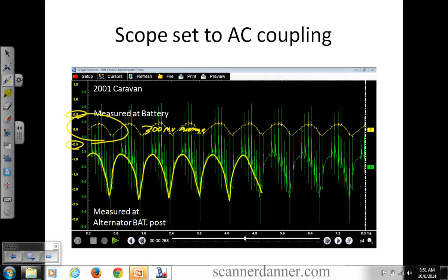So the issue was this van would go into a second gear lockout. Second gear, what they call limp home mode on an electronic shift transmission, would be one that you have park, you have reverse, and you have drive, but it does not upshift. It pulls out in second gear. It doesn't upshift, doesn't downshift. Would be a second gear lockout or second gear limp mode. This is what's wrong with the car.